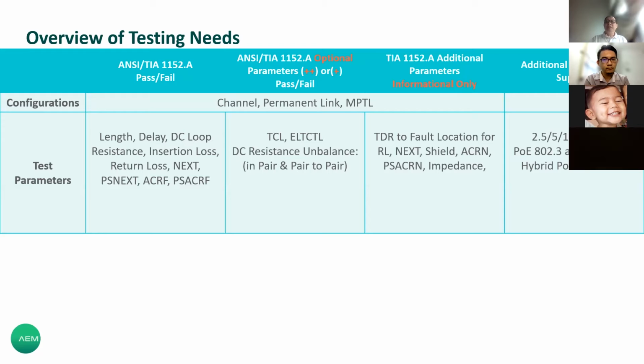Okay, so there are also other parameters on the third column and the fourth column. The third column is already built into the tester itself. Okay, it's basically for troubleshooting. Now, from troubleshooting cables for so many years, usually there are only two major problems when there is a failure, which is one could be crosstalk related or return loss related. So these are the two major failures.